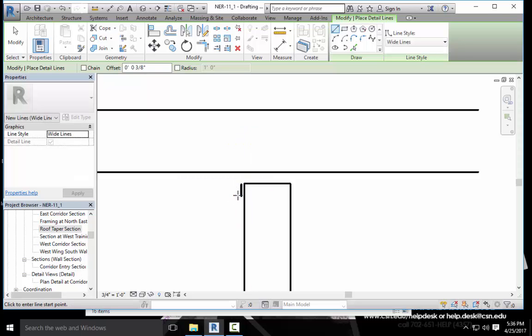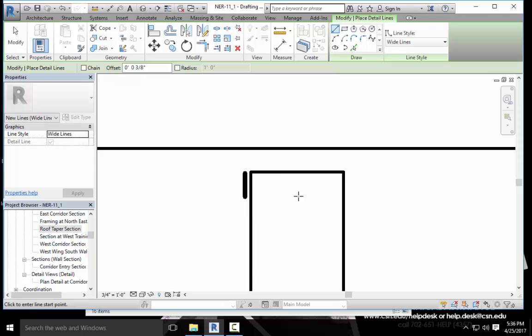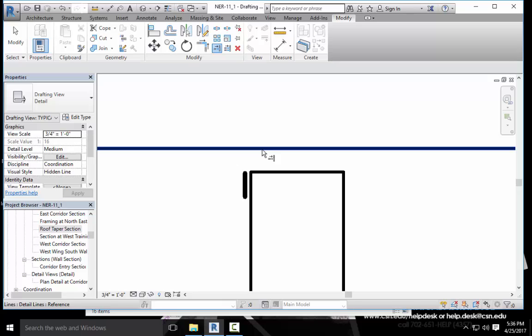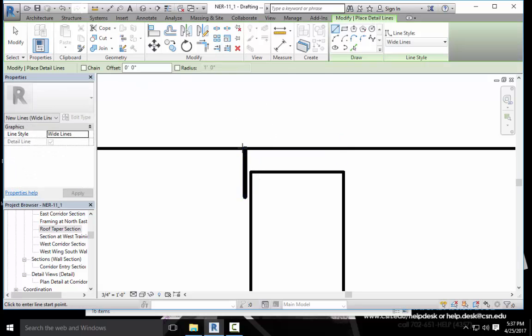You might ask, why 1.5 inches? Because that tells me it's 3 inches long, per the dimensions in figure 11.59. And I know I'm already an inch and a half down. And then I'm going to come here to extend. And then I'll type DL again.